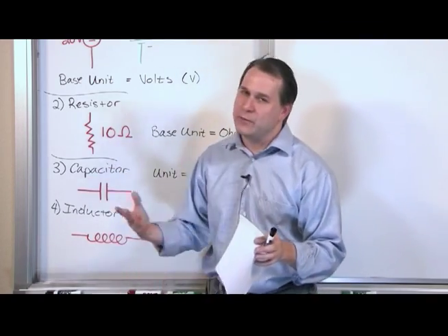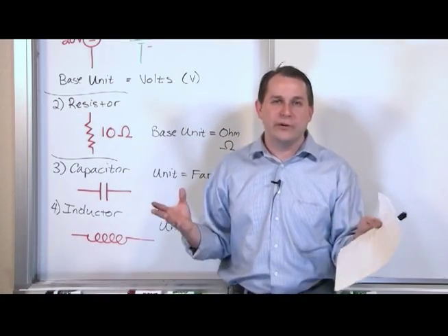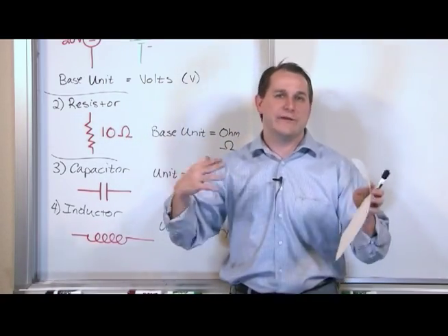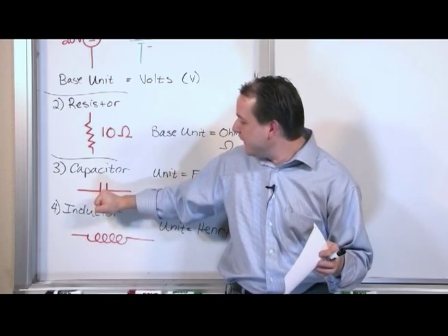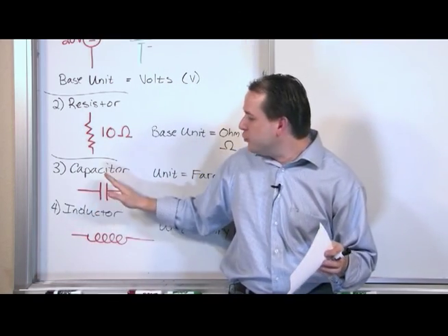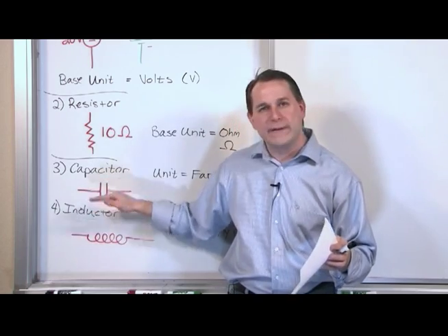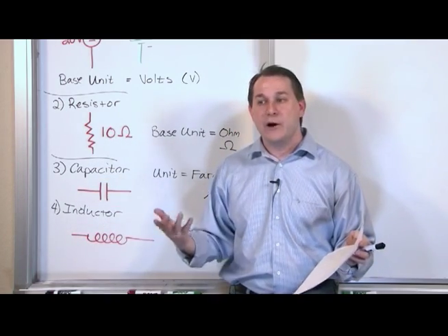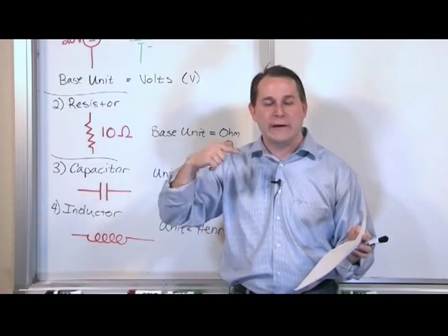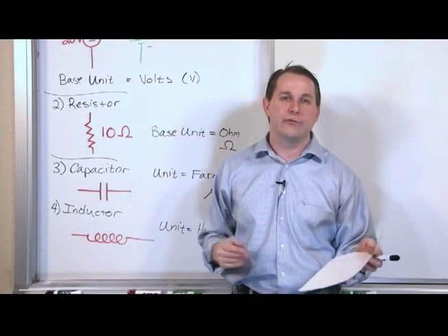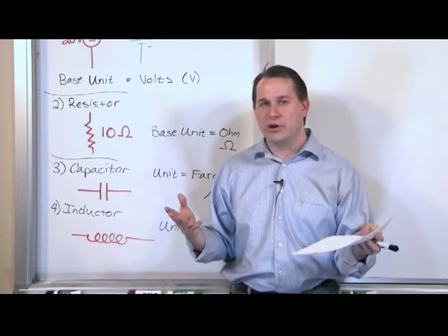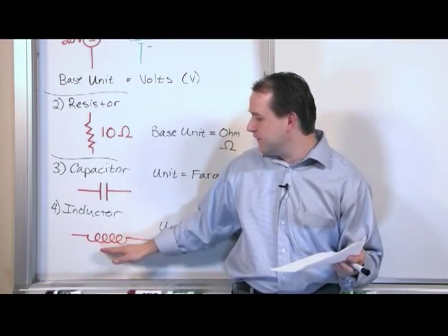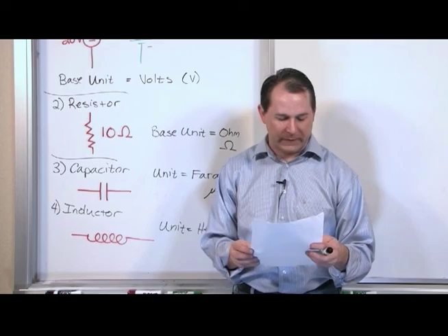All right, that's about as much as I want to say about it, because honestly you can't truly understand it until we do a lot of math and a lot of equations. But big picture, that is what's happening when you tune a radio. You're changing this value of capacitance to perfectly resonate or tune with the inductor that's also there, thereby letting that particular radio station get sent onto your speaker. And that's really what it's mostly used for, at least in terms of radio technology. But inductances, of course, have lots of other uses as well.